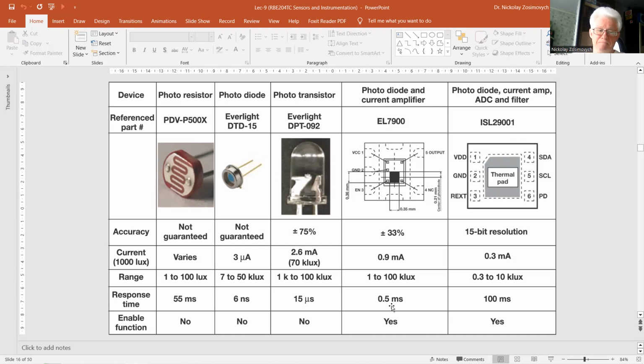Chips with over 60 million pixels are available. CMOS cameras have higher resolution because there are no charge buffers on the chip as with CCD. Moreover, camera and system clocks are synchronized, eliminating the need for a frame grabber and thus increasing the overall frame rate. Cameras will not be discussed further in this class. You could refer to textbooks on this subject and the information provided by the manufacturer.